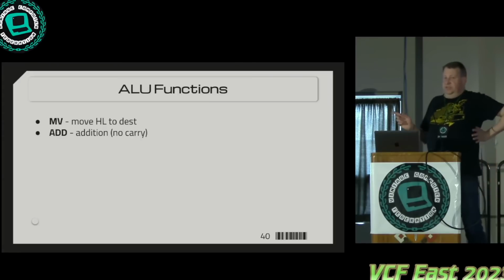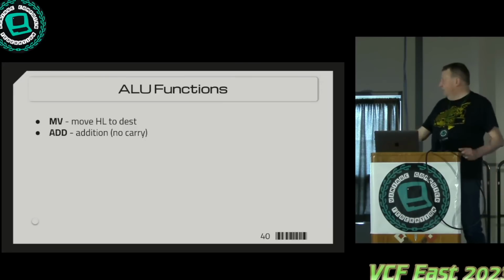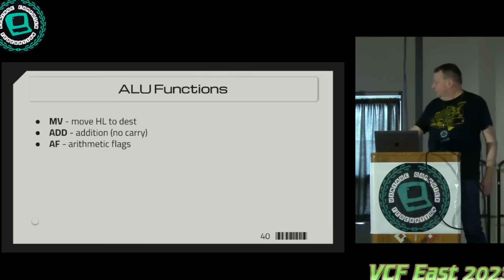There's a problem with this. Because we're using this memory with an 8-bit output, if you add two 8-bit values together, you get a 9-bit one because there's a carry. So we only have 8 bits. So instead of having a subtract next, I have this, so you can do a 2's complement addition. You don't have to waste the whole table to do subtract.